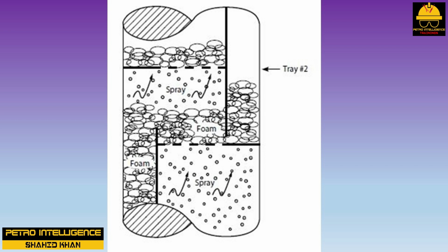When the vapor flow through a tray increases, the height of froth in the downcomer draining the tray will also increase. This does not affect the foam height on the tray deck until the downcomer fills with foam. Then a further increase in vapor flow causes a noticeable increase in the foam height of the tray deck, which then increases the spray height. When the spray height from the tray below hits the tray above, this is called the incipient flood point, or the initiation of jet flooding. Note, though, that jet flood may be caused by excessive downcomer backup.